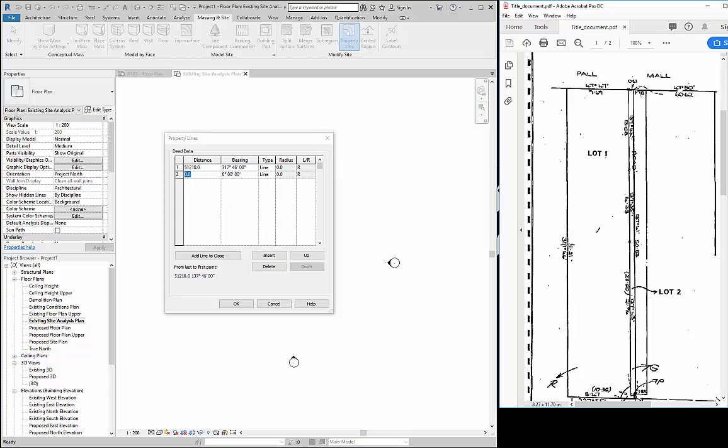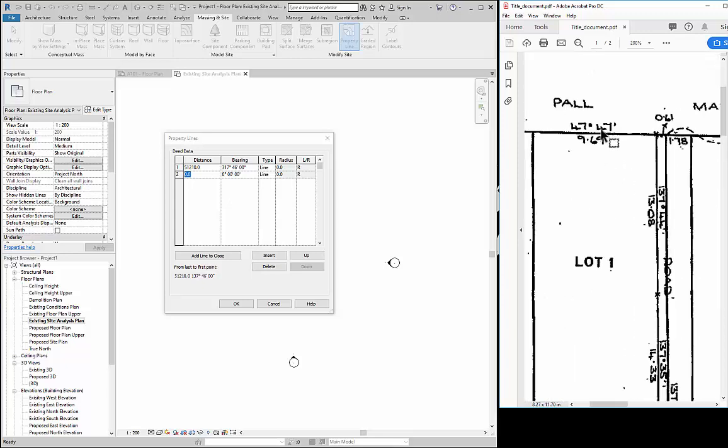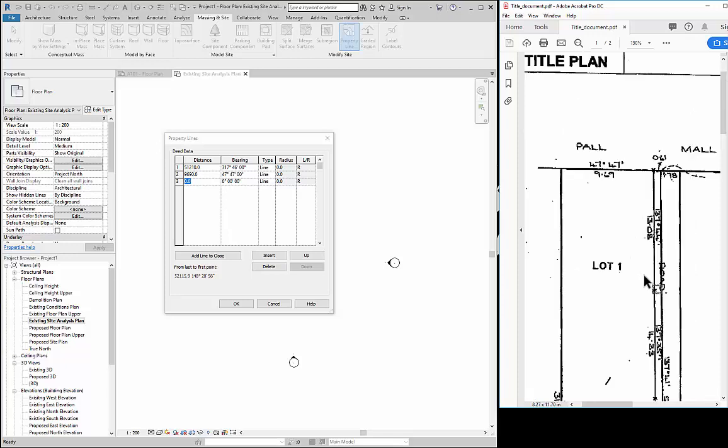So we're starting in the back corner, we're going 317. The next one that we're looking at here is 9 meters 690, 47 as the degrees and minutes. 9690, tab 47 space 47, and we'll insert another line. So from that 969, we're then starting at that corner here, and we're working our way down. So 13 meters and 80 at 137.46. Not sure whether that's 44 possibly.